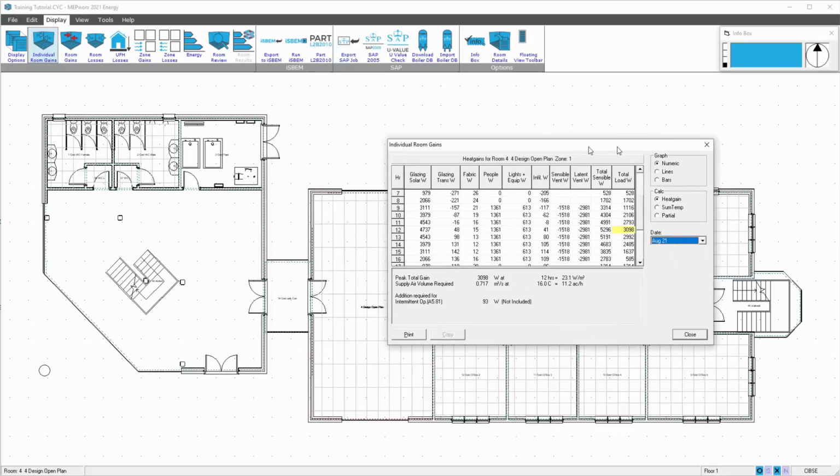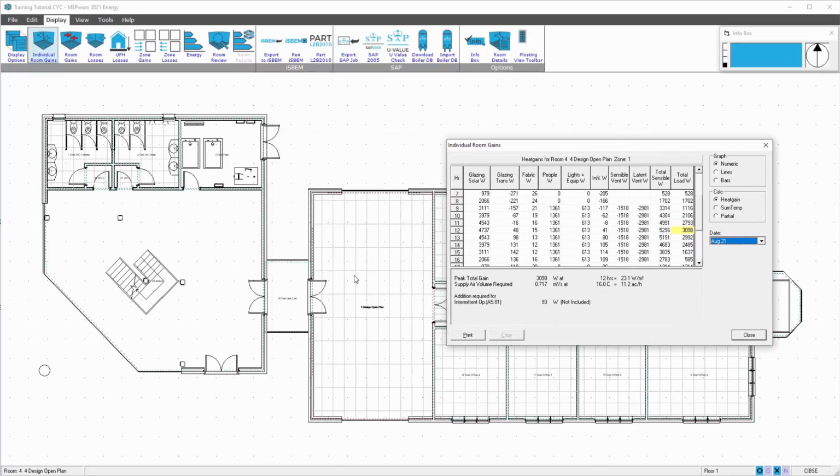If I want to treat the ventilated air into the space for fresh air requirements, I still need a fan coil unit, DX system, split, or whatever, of just over 3 kilowatts to bring that room down to the desired temperature that we've got in the room profile of 22 or 23 degrees.